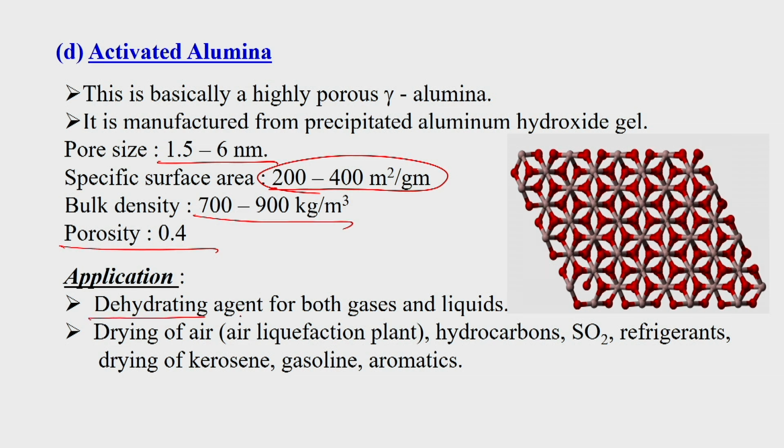Applications are like this: dehydrating agent for both gases and liquids, because it can trap water molecules, then drying of air for air liquefaction plants, and hydrocarbons, then sulfur dioxide, then a few refrigerants, and drying of kerosene, then gasoline, then different aromatics also.